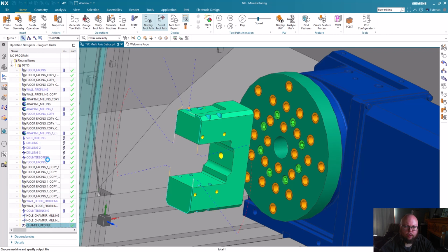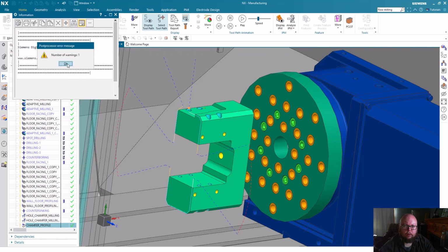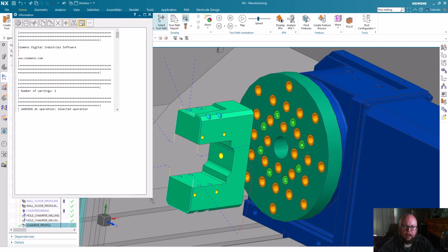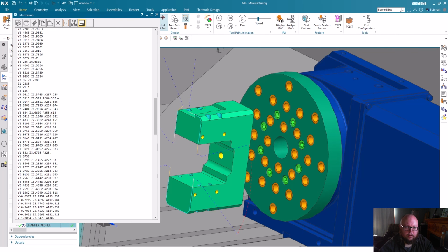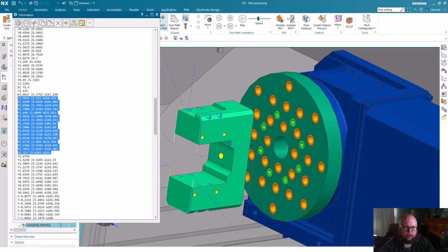So I'm just going to post the code first here. And if you remember looking at the code where I stopped it and we looked at the A motions, in the first segment there were only, I think, 3 A motions. Now for each motion, we are previously at A270, and instead of in one line going directly to A225, we're doing a series of smaller motions.